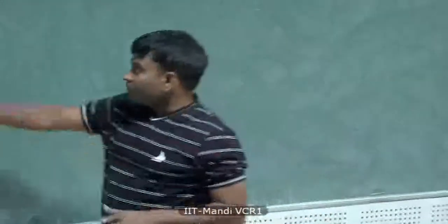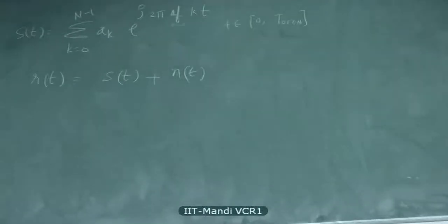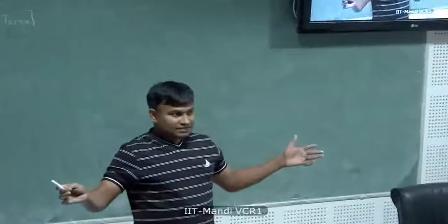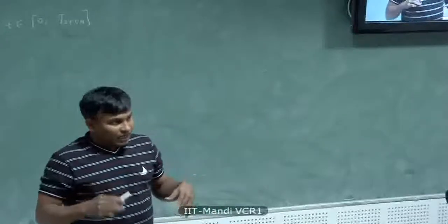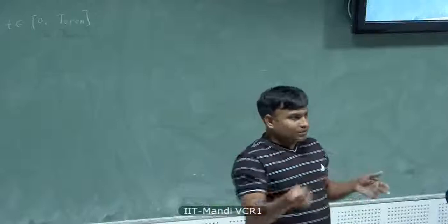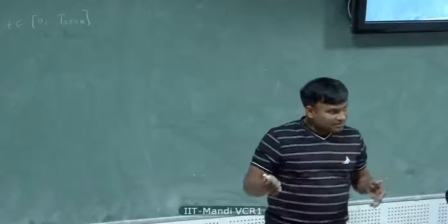So this could be additive white Gaussian noise, which is basically unfiltered noise. Do you know the difference between filtered additive Gaussian noise and unfiltered? Well, if you don't filter, additive white Gaussian noise has spectra everywhere, right? It is flat in the entire frequency band. Of course, this is for a theoretical discussion. And if you filter the additive white Gaussian noise, it gets limited to a certain band, and the power spectra is determined by the shape of the filter.